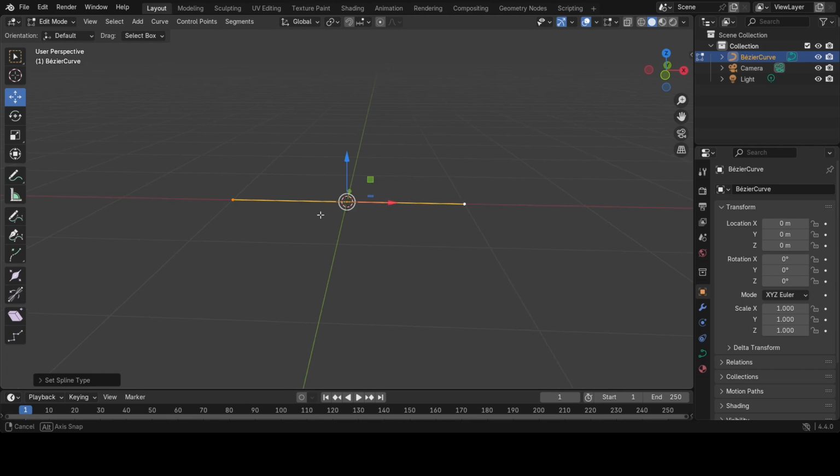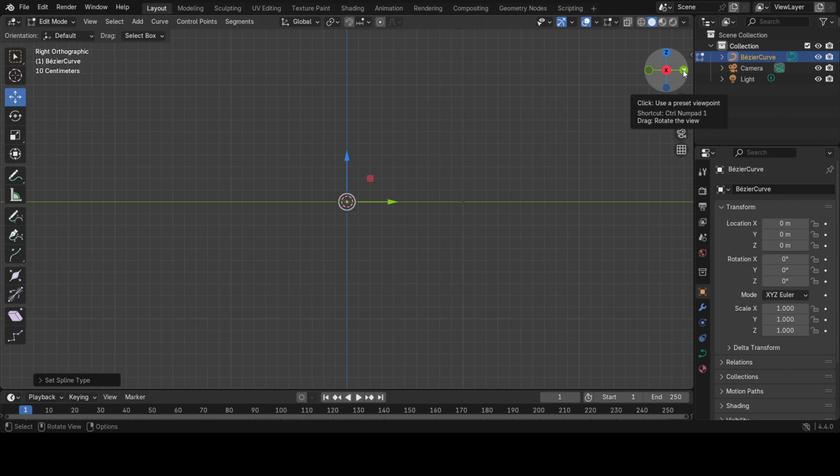Next, what I want to do is go to the front view, and that would be Y, so that we see this from the side. And what I want to do here is first of all, select the side control point, and I'm going to start to construct a profile from which I'm going to revolve on a pivot point, an origin point, to create the shape that I want, which is going to be the bowl.